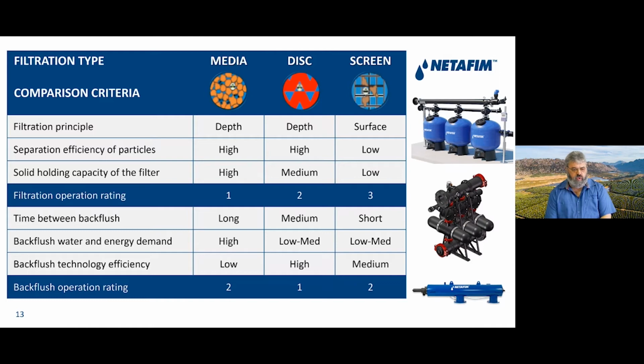The backflush water and the energy demand will be the water that you need during backflush to actually clean the filter. And the energy will be connected to the volume of water and the pressure that you need to do the backwash. So in this case, the lower the rating, the better it is for the end result or the rating.